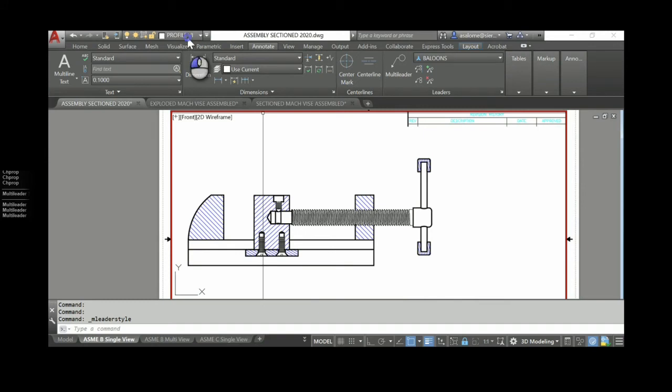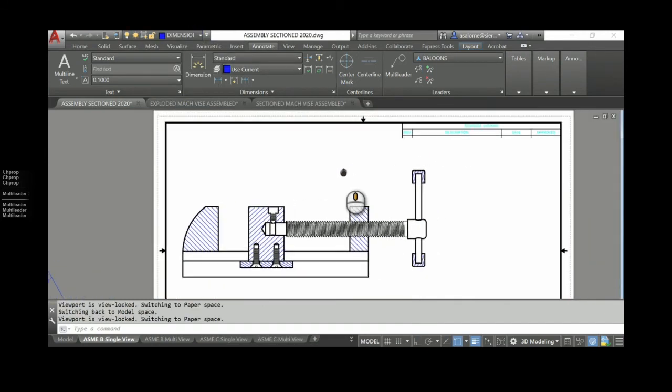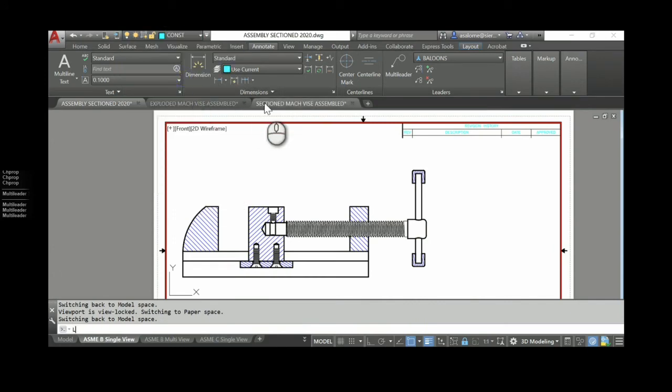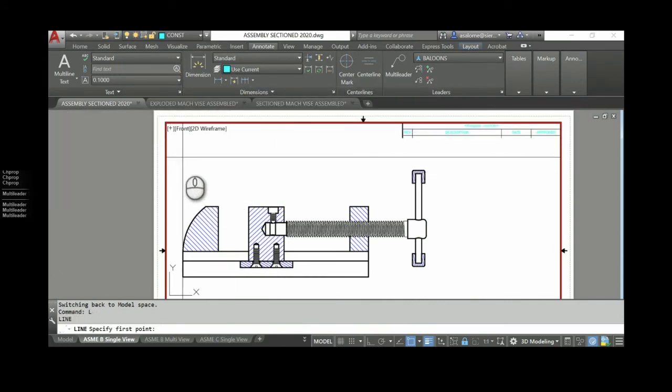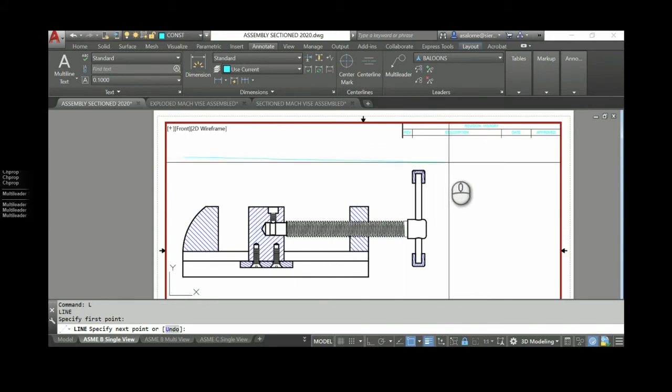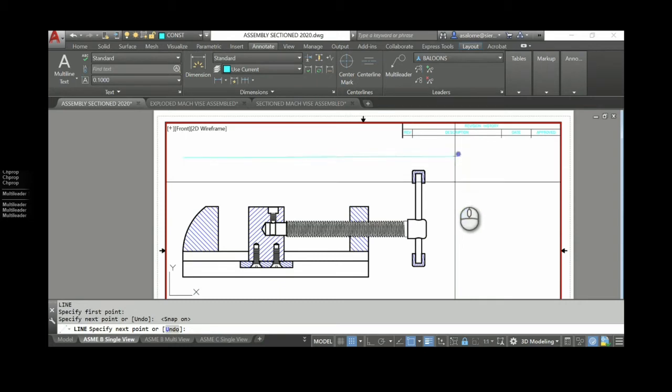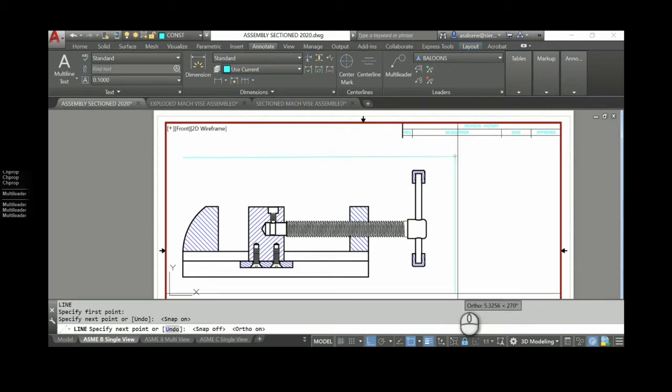Now on my dimensions layer, which I use for putting in balloons, actually, let's go to construction layer and first draw some guidelines here. So your balloons should be nice, neat, straight, and they should line up like soldiers. Can we hit F9 instead of F8?